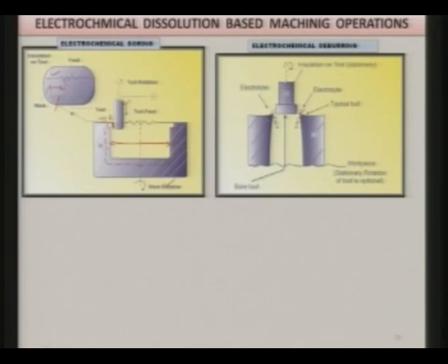Now, these burrs are highly undesirable. They should not remain there. They may lead to the malfunctioning of the component. They may hurt the operator while handling this particular component. So, deburring is a very important operation.